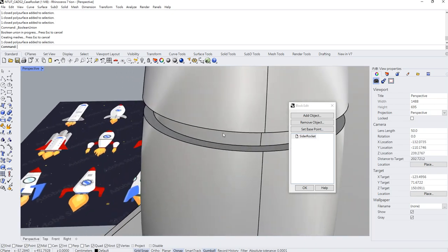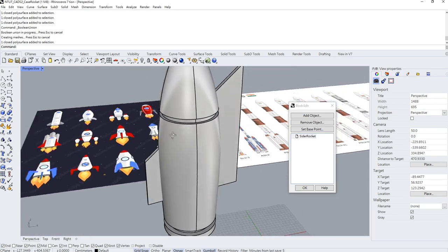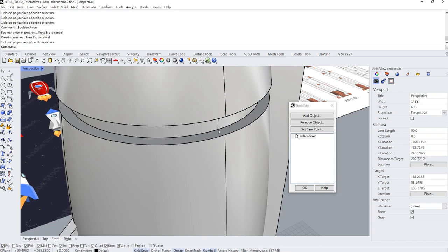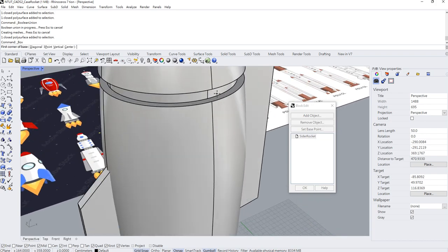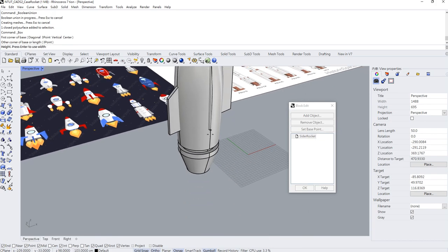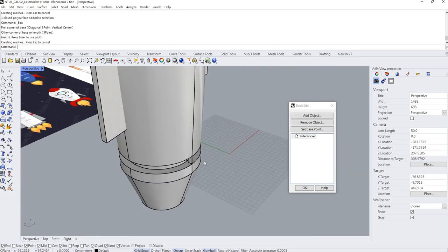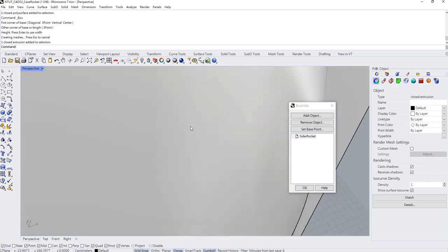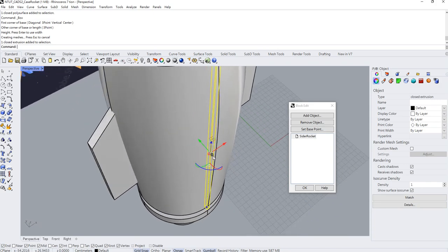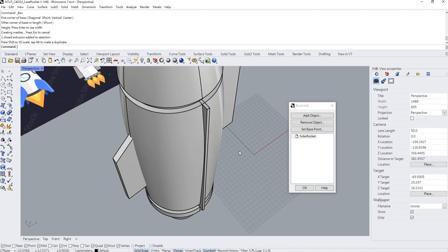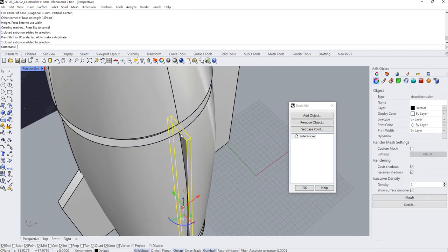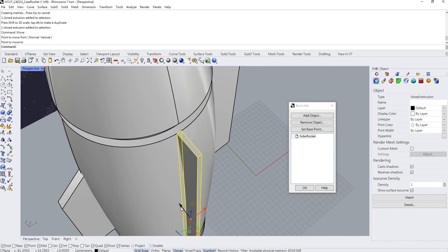The next thing we are going to do is create some carving, let's say carving creases on the booster. How can we do that? I want to use a box. Let's draw a reference box here. We can make this one longer, or just keep it like that, but we have to extrude and make this part bigger in the y direction so that we can use it for carving. This one is supposed to be in the center of the booster, of this edge. So let's use the move tool, select the midpoint, and move this one inside.